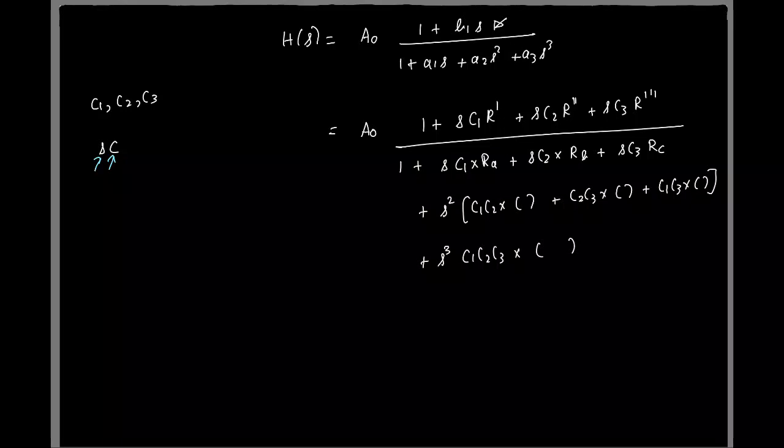And by the way, can I have a C1 squared term here? Why not? It's a product of capacitors, so why can't I have the capacitor multiplied by itself? These things you can prove by contradiction. Say I put C2 and C3 to be 0 in the network. How many capacitors will I have then? What is the order of the system? It's a first order system.